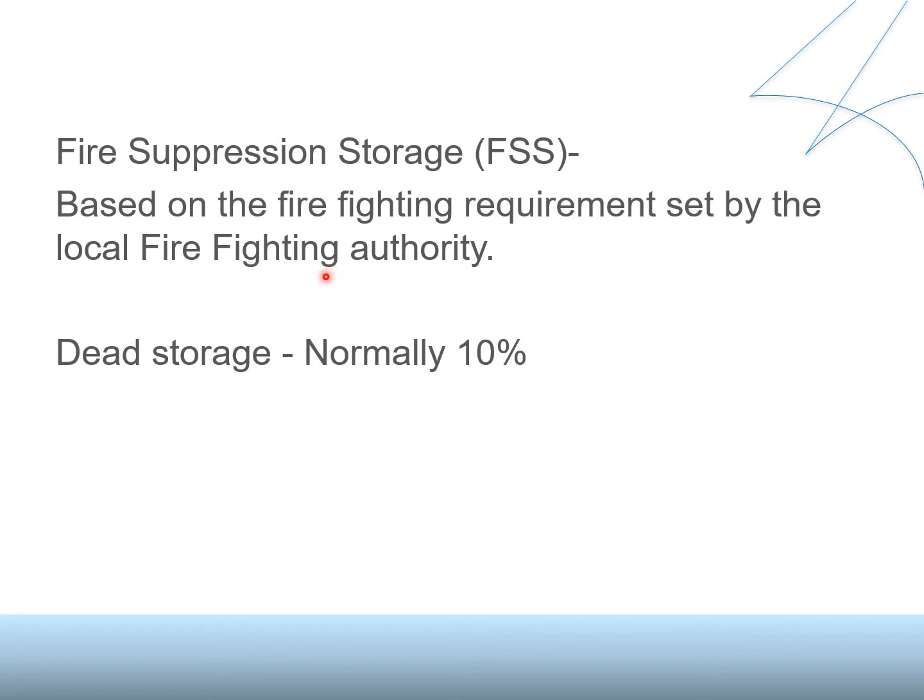We also know the fire suppression storage for the firefighting purpose. We need to have some water, and that is defined by the local fire authority and the councils. For example, in residential area in Queensland, we have like 15 liter per second for 2 hours. So that is the fire requirement. And their storage normally you put 10%. Okay, so all these you add up.